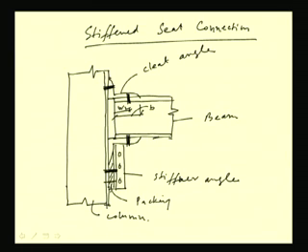We have to connect the stiffener with the column, as well as we have to connect the seat angle with the column. So, in this way we have to make it, and this will be the eccentricity E. So, the new thing we are seeing here is this stiffener.